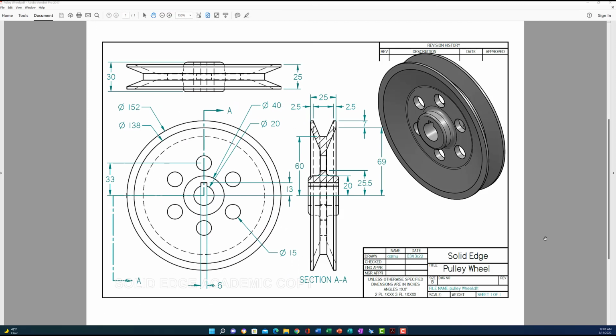In this tutorial video, I will cover how to develop or draw a pulley wheel. To do that, we have to draw the section of the wheel, just 1/4 of a section, and then we're going to use the command revolve. By giving the revolve 360 degrees, you will create the wheel. So we need to draw the section first and do the revolving command.